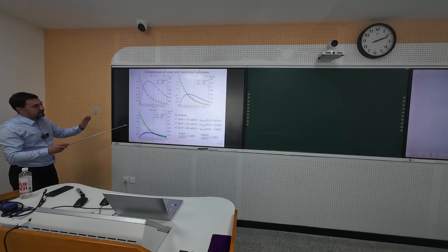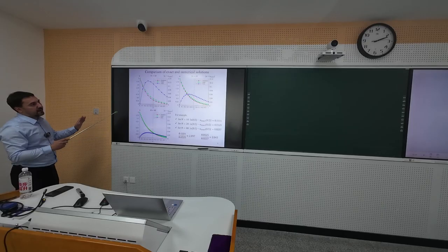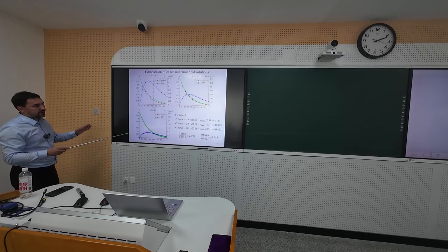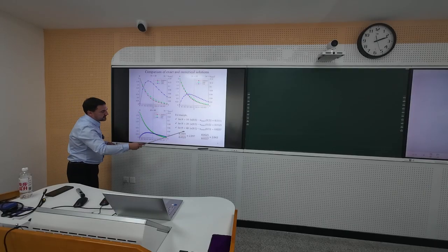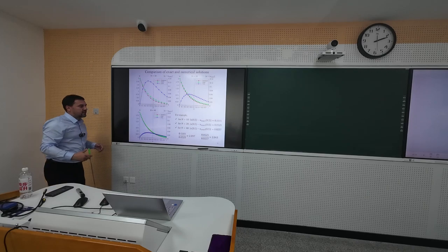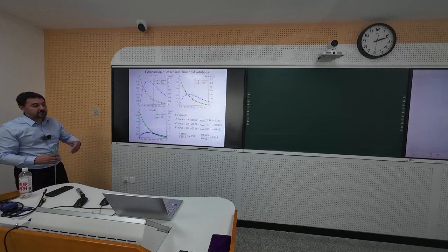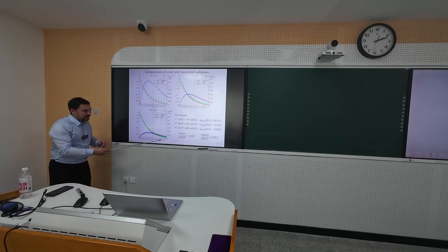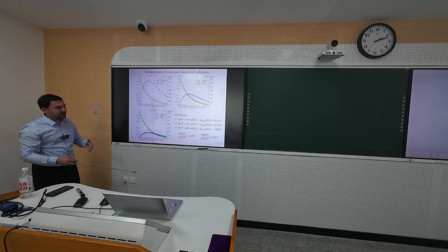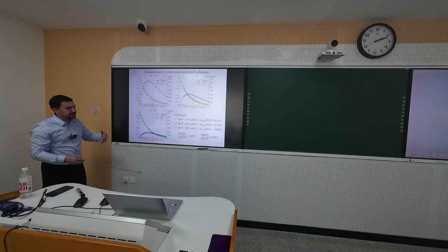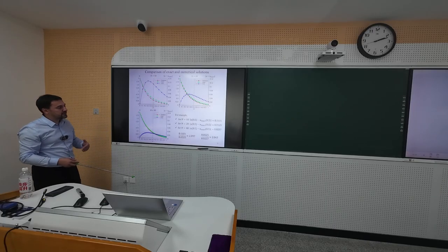So actually, this is the practical proof that the Euler scheme is a first order accurate scheme, because we increased the number of cells or segments twice, and we got a reduction of our numerical error also two times. You shouldn't think that this 2 means that this is the second order of accuracy of the method. No, the order of accuracy is 1.